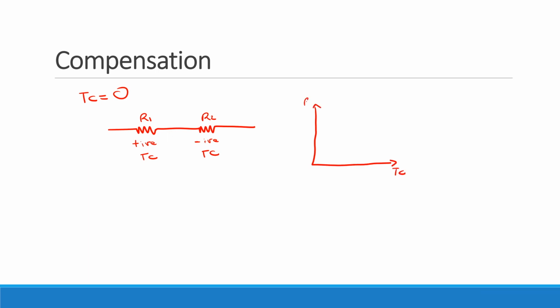Right? So if I look at, maybe I'll do this in a different color just so it's clear. So let's say that's the R1, let's say that's the R2, so that the total resistance does something like that versus temperature, right? So it's exactly what you said. If I knew what those temperature coefficients were, in principle, I could build something that would actually cancel those two things out. And in fact, obviously, you could try and do the same thing with the voltage dependence as well.